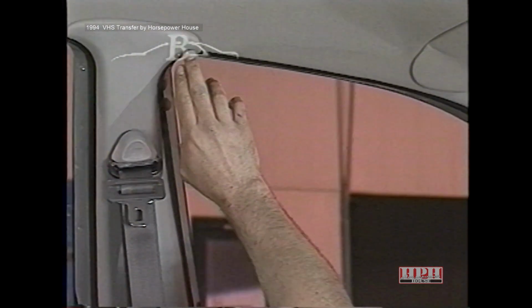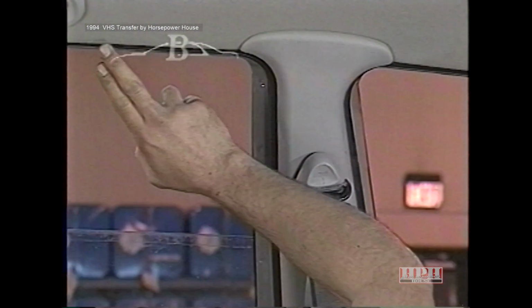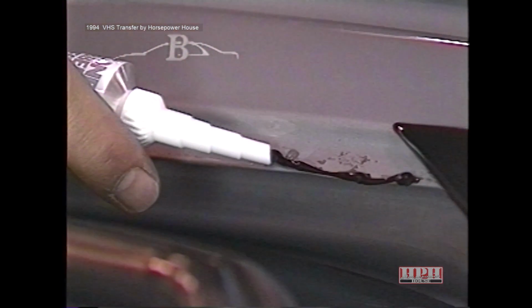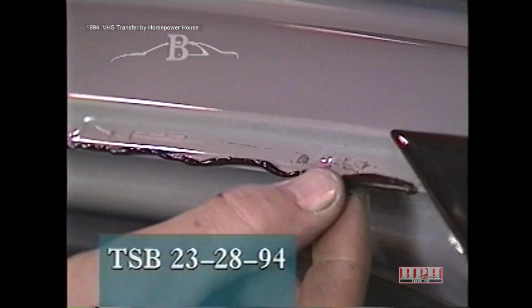If a rustling air noise is apparent above the door opening, at the headliner between the A and B pillars, or between the B and C pillars, the roof rail body seam needs to be sealed. With the roof rail molding removed, seal any gaps in the roof rail body seam with Mopar silicone rubber adhesive sealant, part number 4318025. This procedure was also described in Technical Service Bulletin